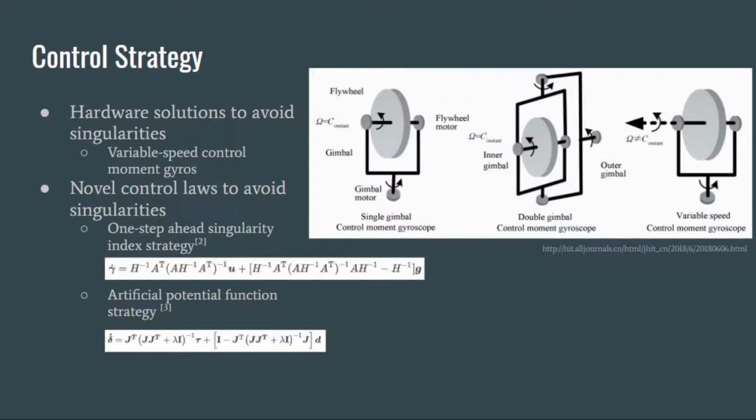To reiterate what Sam said regarding momentum wheels and control moment gyro advantages and disadvantages, a control moment gyro is ideal for control problems that require large torques, such as on large spacecraft or for attitude control in high external torque environments. This relates to control strategy because control moment gyros are less accurate than other control means and are often great for quickly changing a spacecraft's orientation and rotation, but not for achieving accurate pointing. More often, momentum wheels are used for finer degrees of pointing accuracy, but cannot be used to achieve the large torques control moment gyros produce.